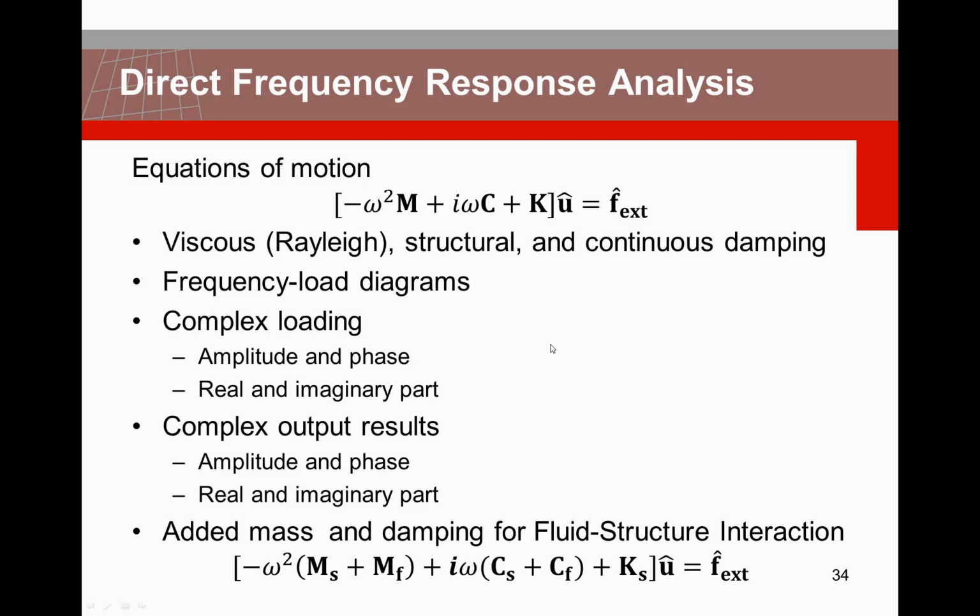So when you have no viscous, structural or continuous damping, and you have enough with modal damping, then you can use the modal frequency response analysis. It will be more efficient in time than direct frequency response analysis. In case you have this damping, or for instance the compressibility in the fluid, then you are more or less forced in the frequency domain to do a full direct frequency response analysis to account both for the added mass and the added damping.